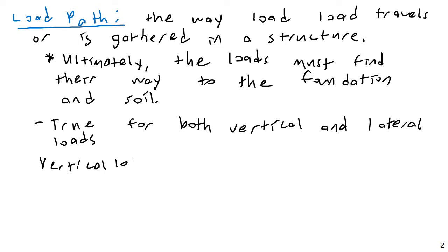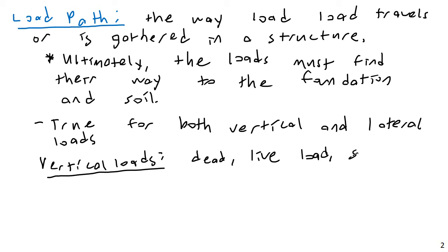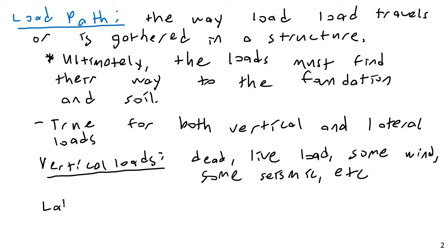Examples of vertical loads would be things like dead load, most live load, some wind, especially roof wind load, and some seismic, etc. For lateral or horizontal loads, we could have many different ones, but the primary ones are mainly wind, at least here in Houston.